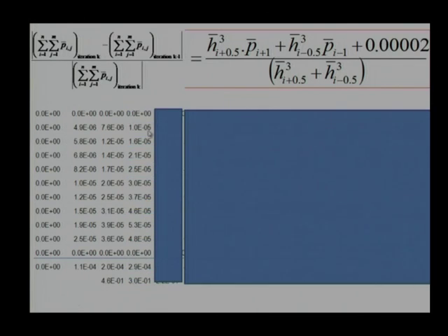We continue it. Iteration number 3, as I mentioned, the first node and last node will be at the 0 value. These are the boundary conditions, we are not varying them, and the remaining other terms are increasing. Instead of 7.6, now the pressure at node number 2 has reached 1.0 × 10^-5, and these all are non-dimensional numbers. It is slowly increasing, and we are able to see the same trend. Maximum pressure occurs at node number 9 instead of node number 10.